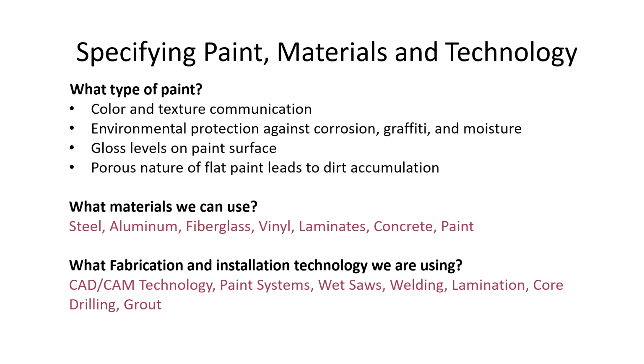It is important to note that flat paint, while it may provide a smooth finish, tends to be more porous and can trap dirt over time. So, we need to consider the maintenance aspects of this paint and choose very wisely. So, I might not use it for a hospital.